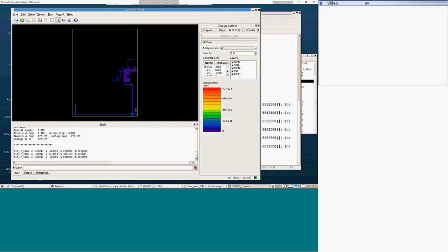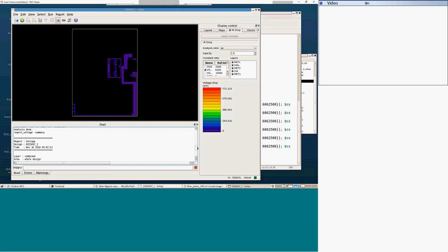So this one is pretty much okay, but if you look at the range of voltage drop, you see the maximum voltage drop in this configuration. I may have created an incorrect configuration. For this one, we see a huge drop of 0.7 volt. So let's see which net it is. You can look into the report, and the report says that this is actually GNDB net that shows such excess drop for the given current consumption configuration.